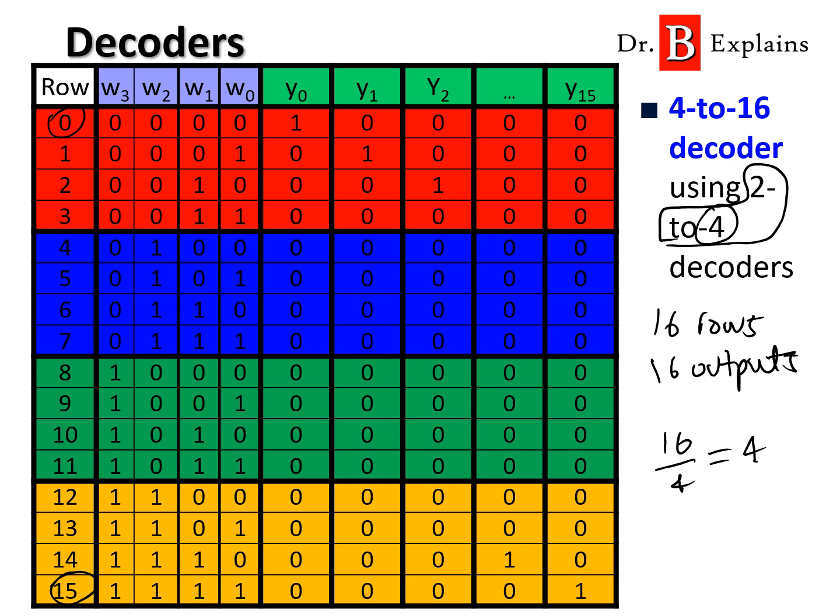Then each of them is going to be controlled by what? Each of these is going to be controlled by another decoder. So we need to be able to differentiate between this part, the blue, the green, and the yellow, right? So how to differentiate that? With these two values. Look at this, we have a 0, 0, a 0, 1, a 1, 0, and a 1, 1, okay? So let's look at the diagram.